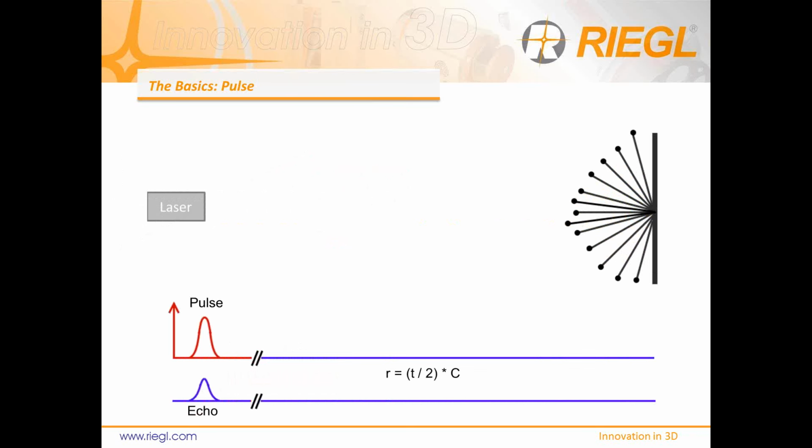Now, the time of flight format's really simple. Range equals total time of flight, t, divided by 2, right? So that's just how far it went out. We don't care about how it's come back, the time, all that, but times the speed of light, and that's your distance. Very straightforward. But we take this a bit further, and we compare the returned echo with the pulsed echo.